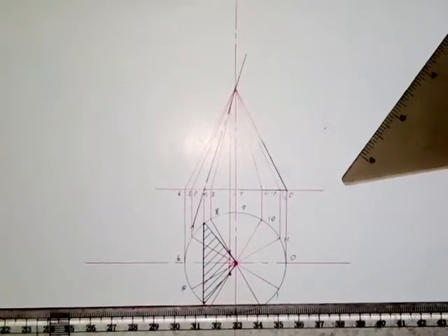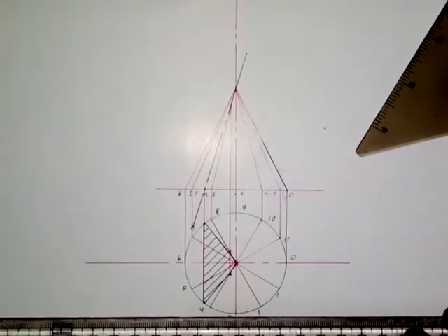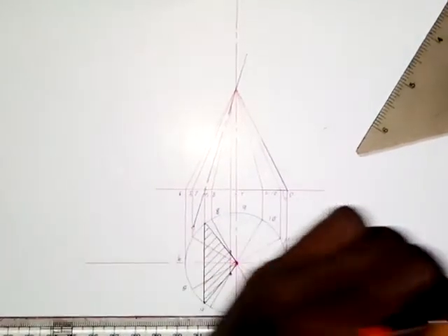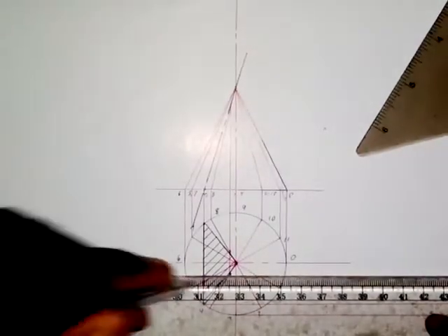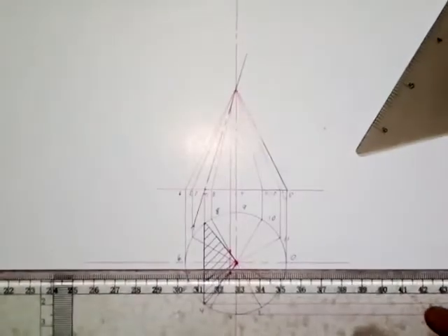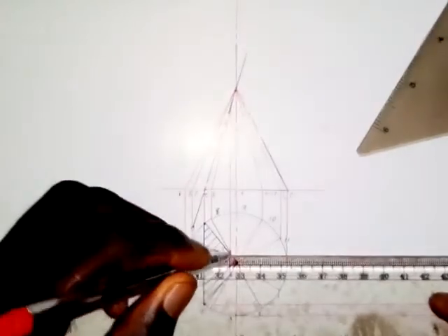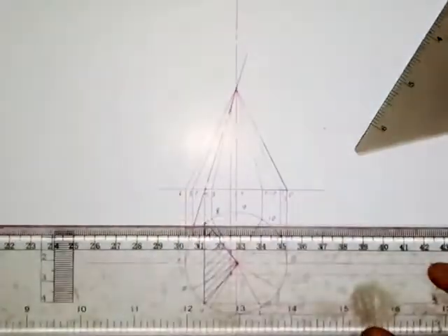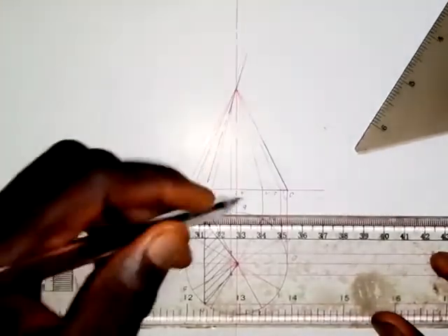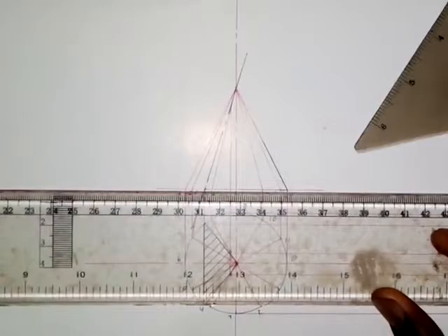So what about in the end elevation? So we want to produce the end elevation, how it's going to look in the end elevation. So I'm going to draw a horizontal line from here, and from this point I will draw a horizontal line. Also from this point I will draw a horizontal line. So this center line, I will draw a horizontal line. So from this point here, and then from this point, I will draw horizontal lines. From here, that is point 9, I will draw a horizontal line. Then I need to extend these horizontal lines.